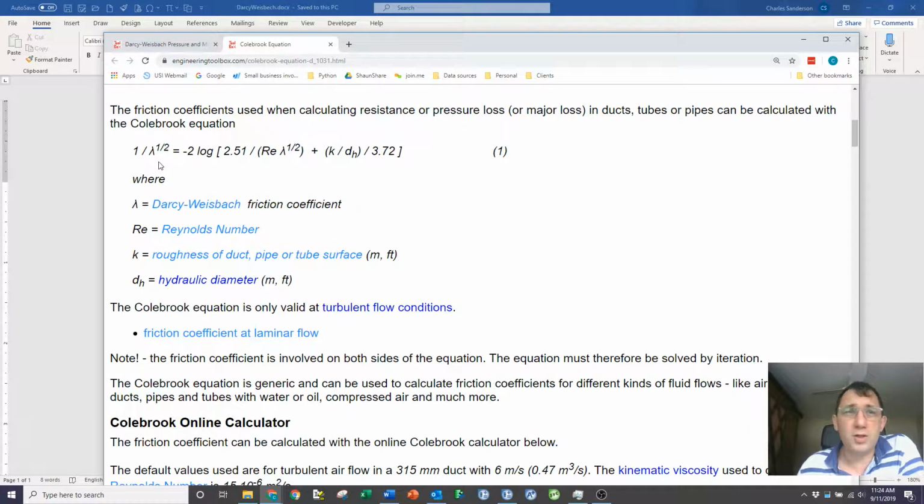That Colebrook equation is one of these typical engineering correlations that's a bit of a mess with all sorts of challenging terms. I'm dividing by things, I'm taking square roots, I've got logs of things, so there's lots of potential for the maths to get messed up if I get negative values or zero values feeding into some of those systems.